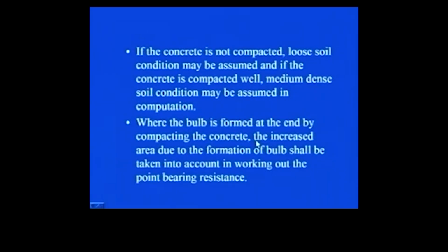When the bulb is formed at the end by compacting the concrete, the increased area due to the formation of the bulb shall be taken into account in working out the point bearing resistance. Obviously, that is why the bulb is being provided at the base of the pile.